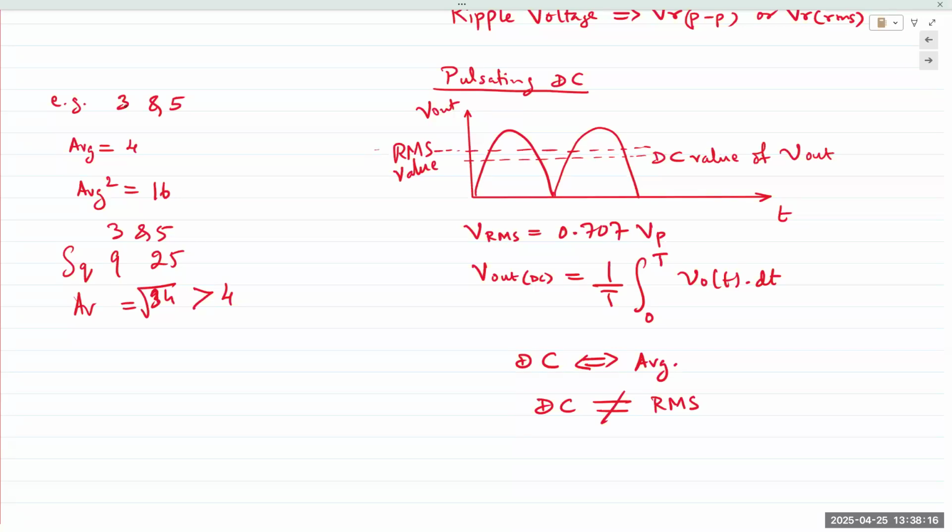There's a lot to think about, but you can review this outside of class and let me know if you have any questions, okay? But anyway, there's a purpose for the RMS values. That's what I'm trying to get at. All right, so let's go to the example problem. All other equations apply exactly as they are. If you're taking RMS values, you work in RMS, and you can apply Ohm's law, KCL, KVL, everything applies exactly the same. If you're using peak values, again, Ohm's law, KVL, KCL, everything applies exactly as it is. Okay, no difference in the laws.